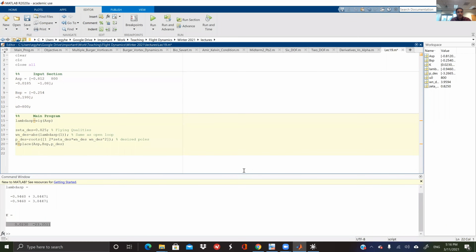Then let's do some simulation. Okay, let's do some simulation. The command that I like for simulation is called LSIM. It takes what? It takes your system, my system. It takes the input. It takes the time. And it takes initial conditions. So let's define these and do LSIM here. Please, if you have any questions, stop me. I'll upload this file, but we're just doing it together.